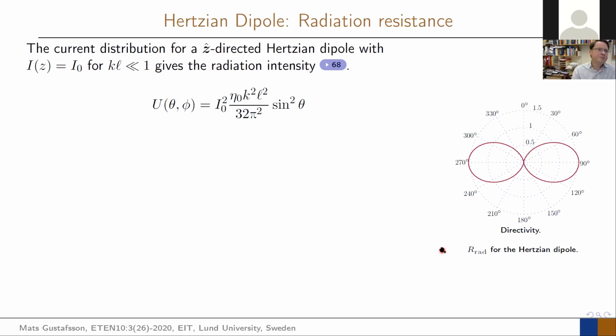So let's do that. What we did in the last lecture is that we calculated the radiated power for a short antenna, the Hertzian dipole. So let's assume now that this is really short. You can do this for slightly longer ones also, but it gets incredibly difficult. So in this course we do this because here we gain understanding. If it's longer, we put it into FEKO. So this part you should do. I will not remake this now because we did calculate this in the previous lecture.